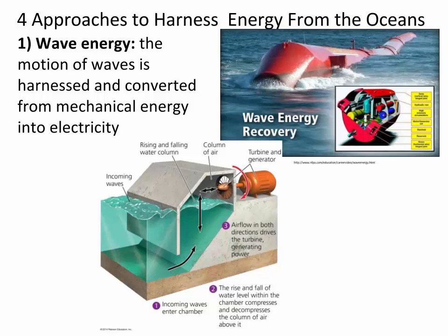This facility captures the energy from waves coming to shore by funneling the waves into a narrow chamber. The rise and fall of the water level inside the chamber compresses and decompresses air. This causes air to flow through the chamber. The airflow drives a turbine on the outside of the chamber to generate electricity.